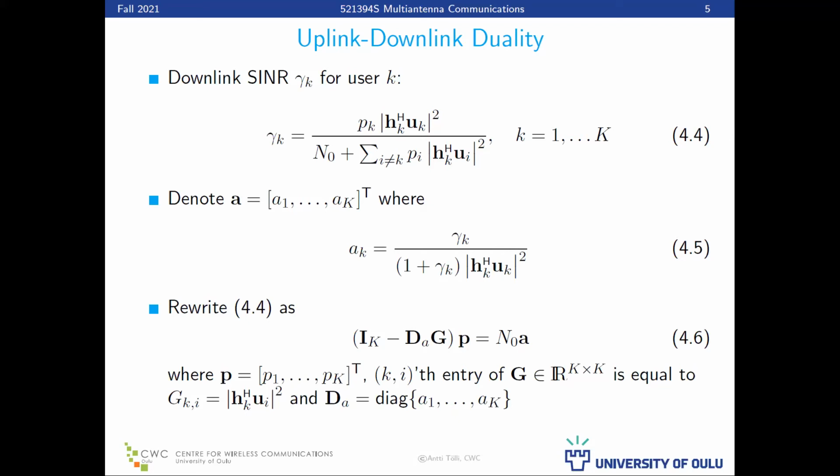See this? In the downlink, because we are sending a superposition, we are broadcasting the signal X. And this broadcast signal is received at each user over the same channel H_k. So the interference comes from these other beamformers that are simultaneously broadcast to other users. This is the difference that we will use in the uplink-downlink duality a lot. Otherwise, it's the same, if these beamformers are normalized.